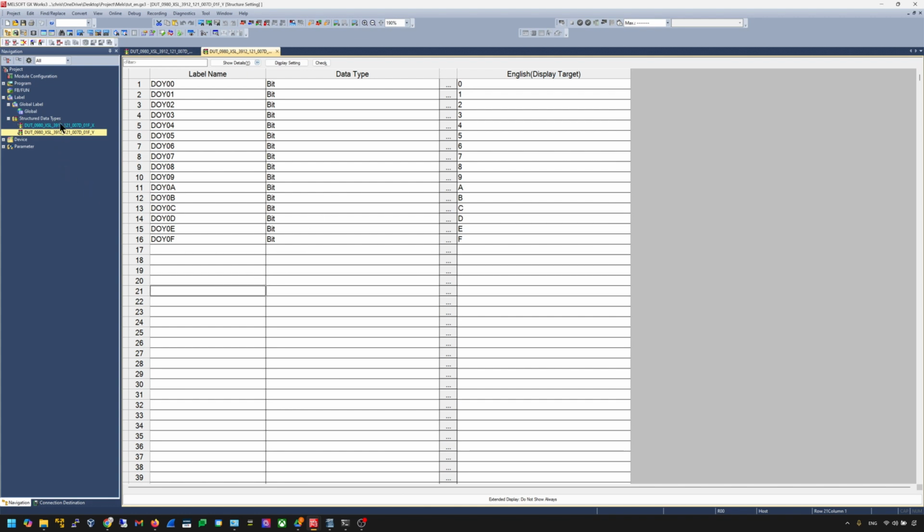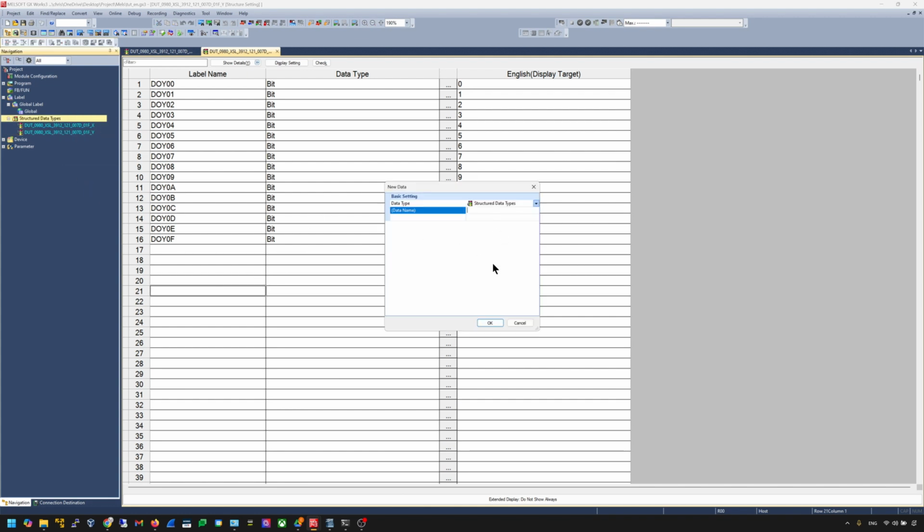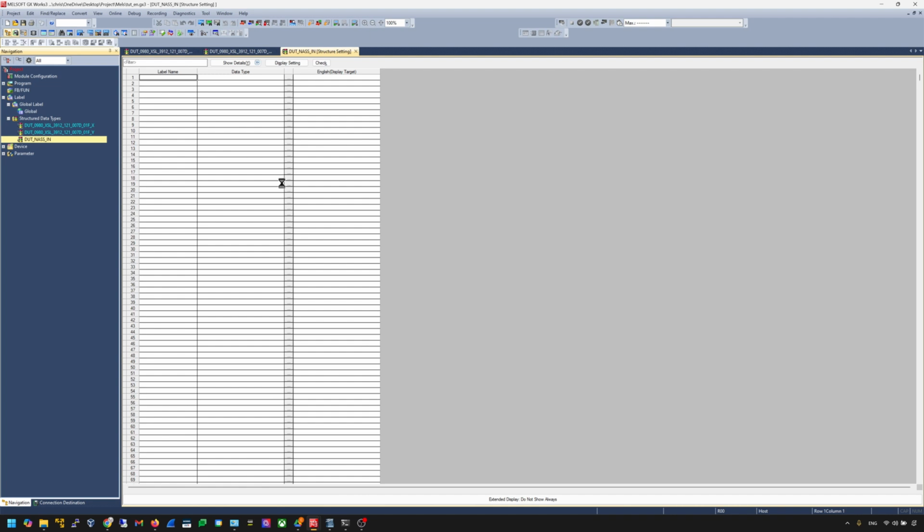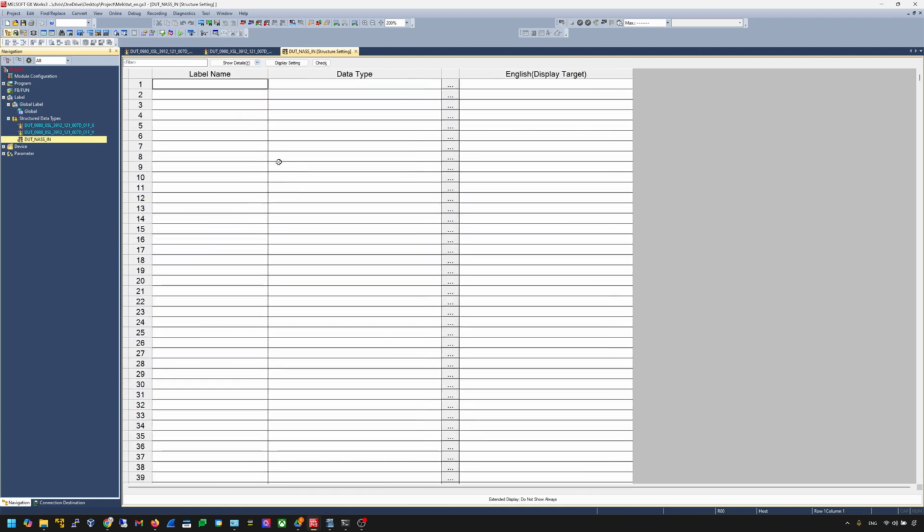The next one I would like to use is the data type of my Molex IO-Link smart controllers, the input data type. You can see I use it so many times in the tutorial, so I just place it here. For this input, you can get the status, whether there is a short circuit or not, whether there is an open circuit or not. You can also get all the states of that module.